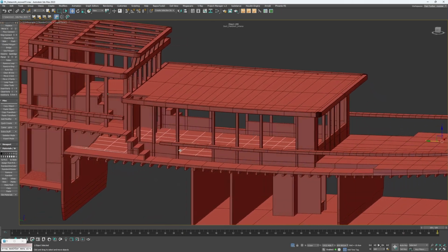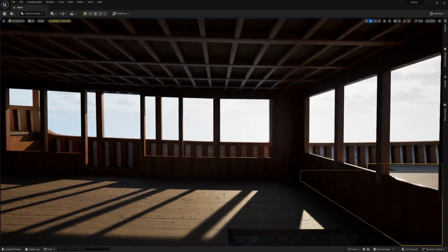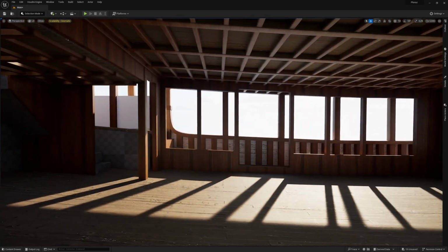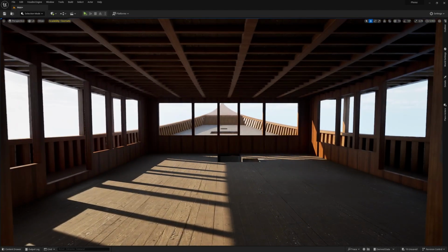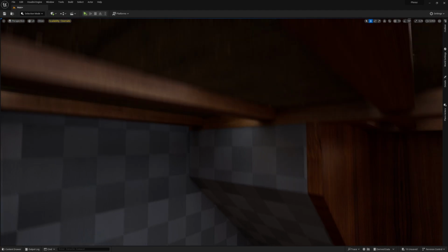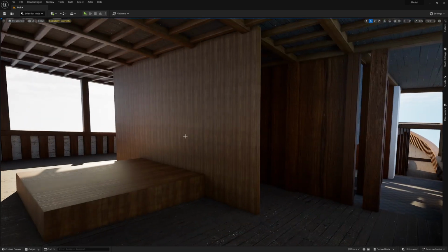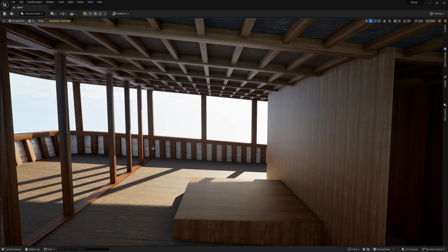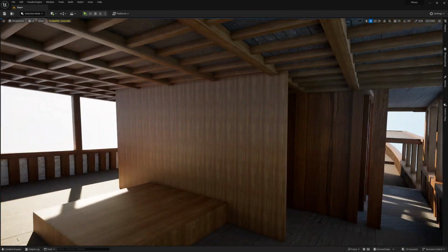We have the same concern in the living area, which has a more acceptable inclination, let's say, but you see you have a difference, and you really feel that you are going down. So the question for this point: should we create some flat area somewhere we would like to, at the cost of losing a bit of ceiling height? We need to take that into account. But honestly, we have a great ceiling height, so it's a solution we could use if needed.